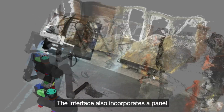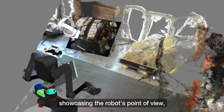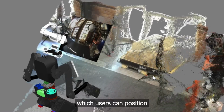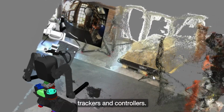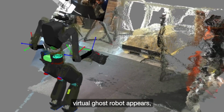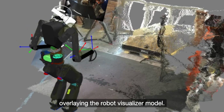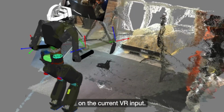The interface also incorporates a panel that presents the camera feed showcasing the robot's point of view, which users can position according to their preference. The user can operate the robot using VR trackers and controllers. During kinematic streaming, a yellow virtual ghost robot appears, overlaying the robot visualizer model. The ghost serves as a reference representing the solution found by the IK algorithm based on the current VR input.